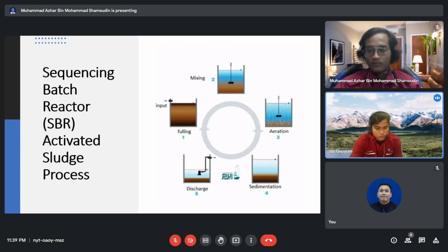Once the reactor is full, it behaves like a conventional activated sludge system, but without a continuous influent or effluent flow. The aeration and mixing are discontinued after the biological reactions are complete. The biomass settles and the treated supernatant is removed. Excess biomass is wasted at any time during the cycle. Frequent wasting results in holding the mass ratio of influent substrate to biomass nearly constant from cycle to cycle.